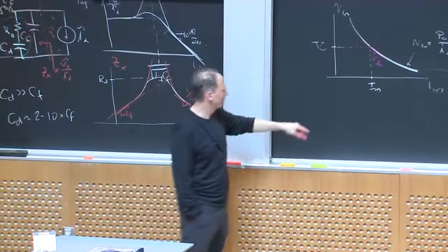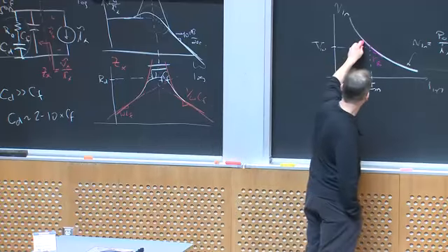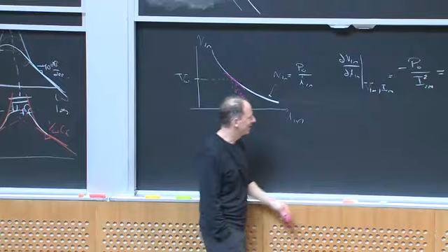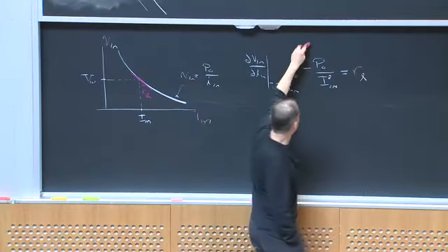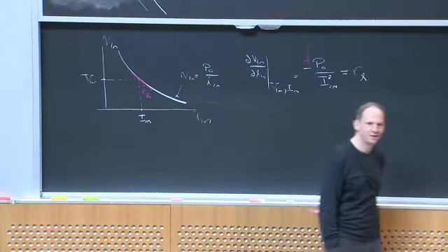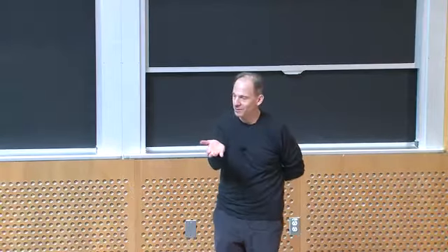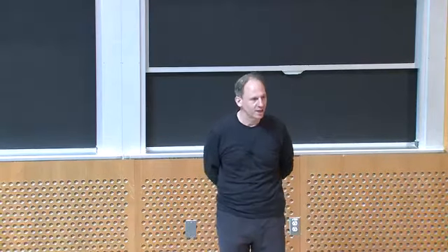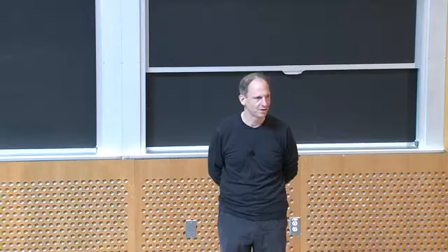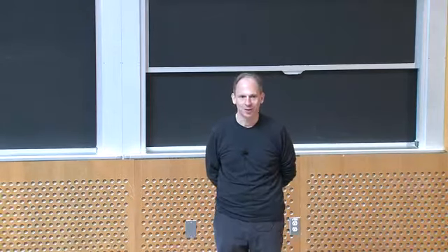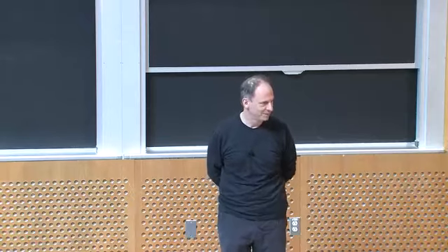Anybody notice anything about this resistance here, R sub L, this slope? It's negative, right? So this negative sign is the source of a lot of pain and embarrassment, because essentially, from a small signal perspective, the power converter looks like a negative resistance to the source. And negative resistances tend to make you unhappy because why? Because they can make things oscillate, all right?